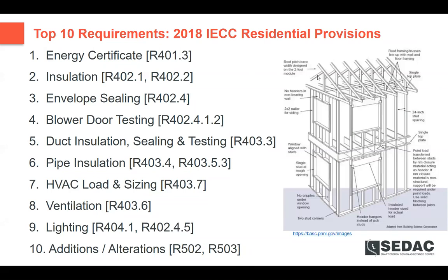Here's a question about old construction. Again, if you're not doing anything that's touching the outside walls, then the outside walls don't have to be brought up to compliance. Now, if you're doing windows, then those windows need to comply, but just installing new windows does not require you to insulate that wall. And there's that exception: even if you do expose the cavity, as long as you fill the cavity, that is considered compliance. That is a good exception to be used.